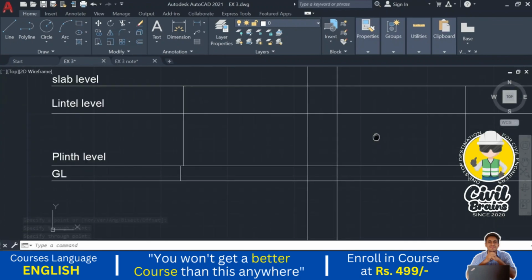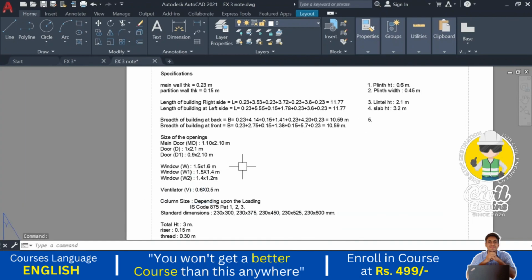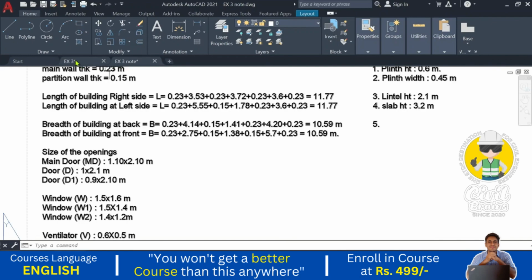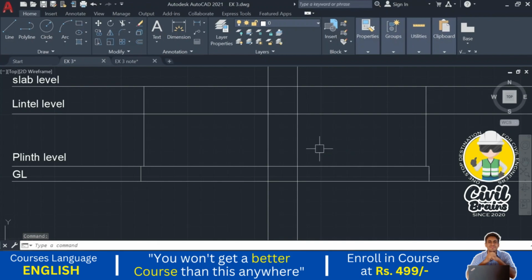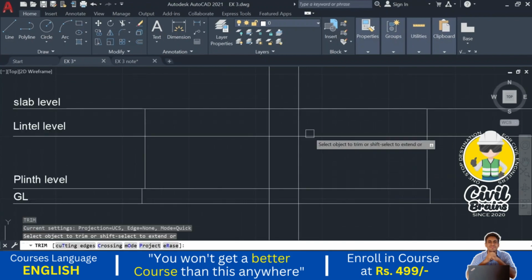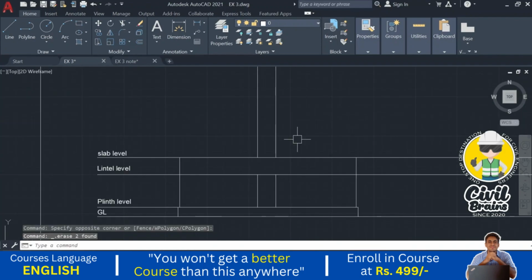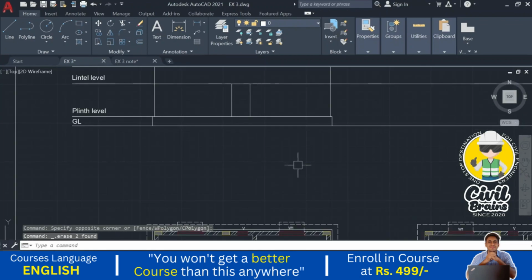Okay, so what is the height of the door? The height of the door, I just show you here. So here the height of the door is 2.1 meter, that is the main door. All the doors' height is 2.1 meter. Okay, so we just take 2.1 meter, that is the bottom level of the lintel. Remaining things I just trim, this I don't want. Okay, delete it. So I just draw the door over here.